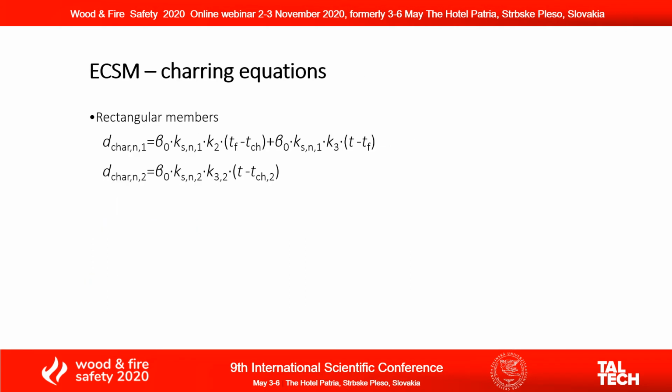The equations to calculate the effective cross-section are developed based on furnace fire tests and thermal finite element simulations. The design model for rectangular members was developed by Mattia Tiso as part of his PhD project. He also developed a qualification methodology for insulation materials. This allows the engineer to consider the protection offered by insulation materials based on their performance and not only the source material, because previously we used to differentiate mostly only stone wool or glass wool.